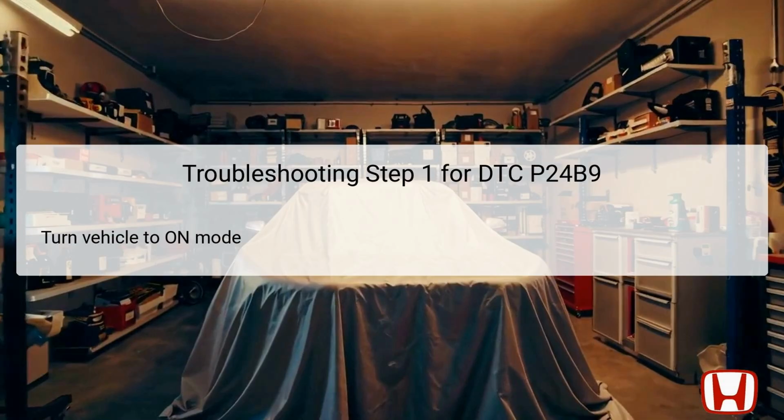This action supplies power to the vehicle's electrical system and allows the PCM to perform self-diagnostic checks of the EVAP system, while also facilitating the monitoring of various sensors. It is crucial that all systems are active in this phase, as it allows the technician to capture the necessary data required to assess the condition of the ELCM pressure sensor and its functionality.